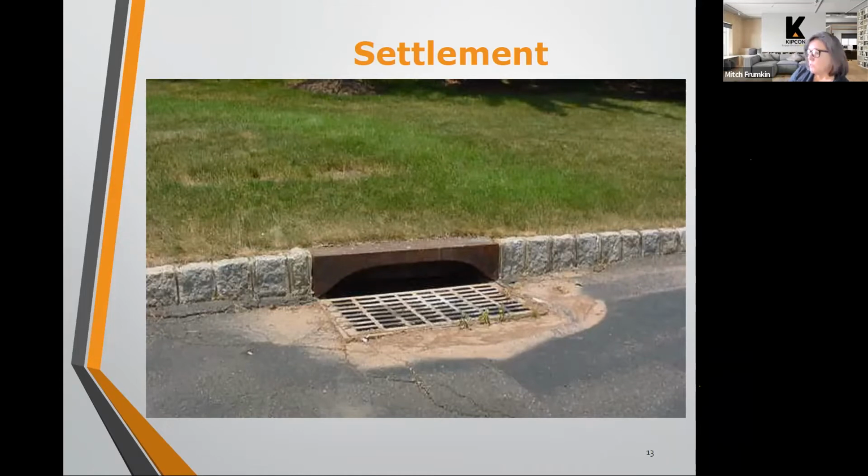Also, I want to mention that catch basin repairs are actually a part of a pavement project. We consider that part of the pavement project because the condition of the catch basin boxes can affect the performance of the pavement over time.